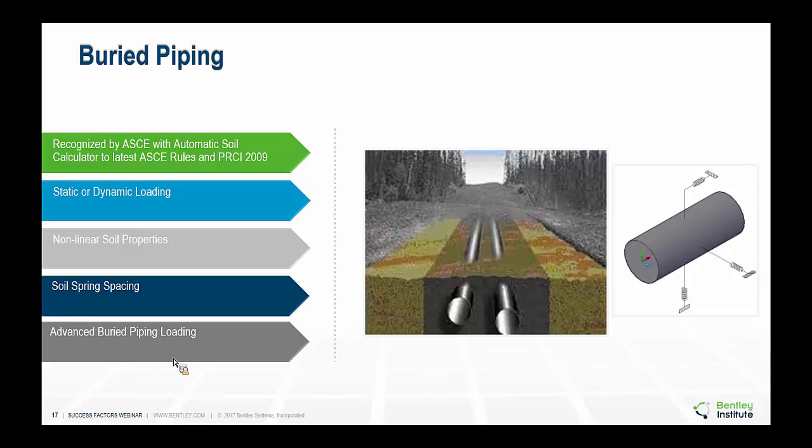Separate properties can be defined for longitudinal soil resistance, representing longitudinal cohesion, for transverse horizontal resistance, and for transverse vertical resistance. In the vertical direction, different properties may be specified in the upwards and downwards directions to account for differences in uplift and downwards bearing behavior.